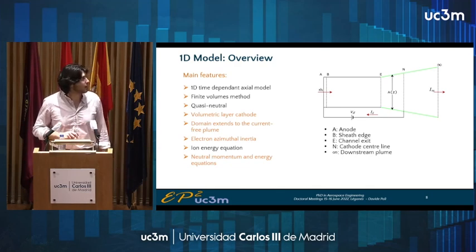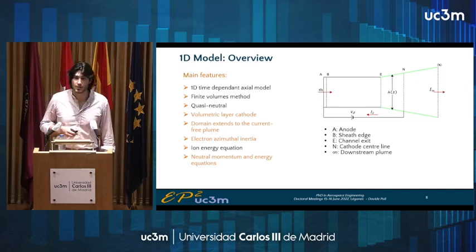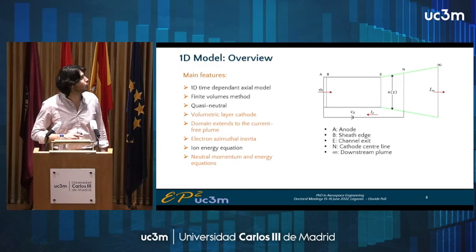I also characterize better the heavy species by introducing an ion energy equation, but also neutrals momentum and energy equations, accounting for the effects of ions that recombine at the wall and re-enter the domain as neutrals, and can deposit some energy in the neutral flow.